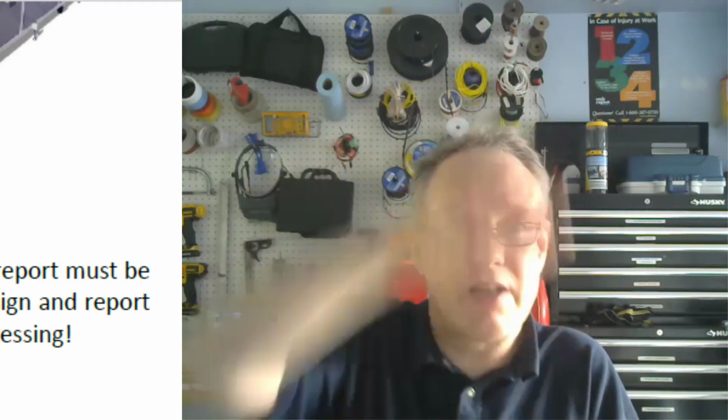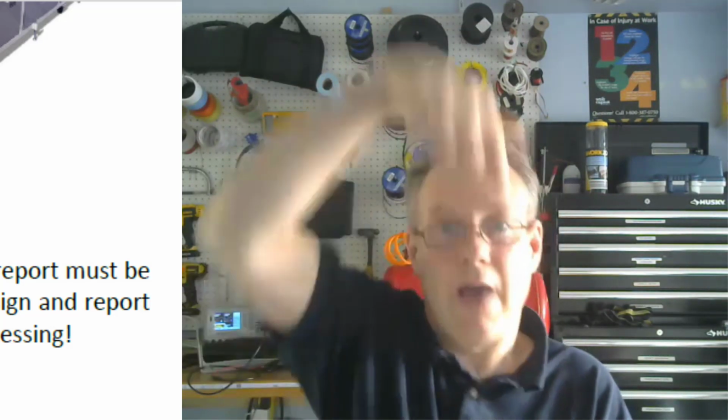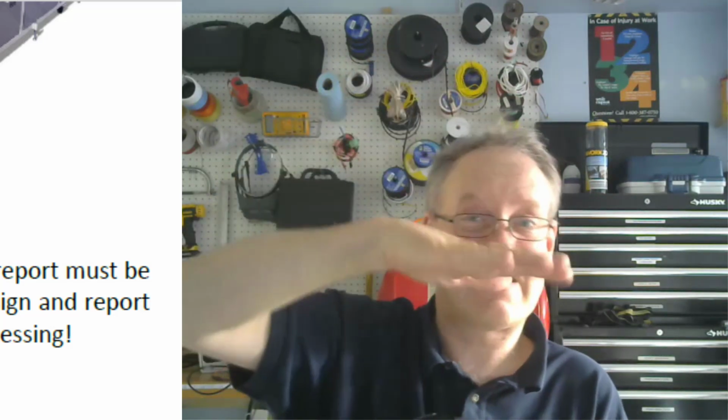Now it's perfectly aligned, so when the stamp comes down, it's going to hit in the exact right place. So here we go. We've got this situation. There's one actuator that does this, and then a clamp comes and clamps it. And then a stamp actuator comes down, it stamps, holds for a certain amount of time, and then comes back up again. Now that stamp is a heavy stamp. It weighs like 200 pounds.